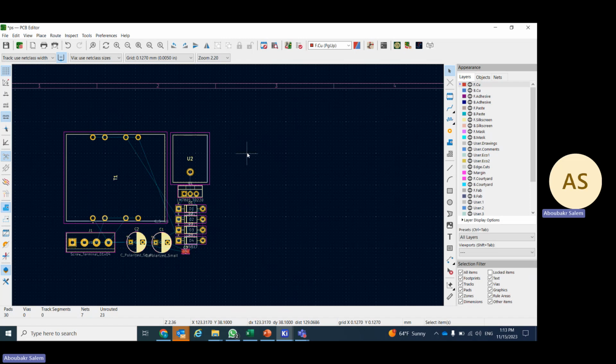Okay, so if I'm satisfied with the orientation like that, guys, let's make the border edge now. For the border edge, we should first select the edge layer. If you go to the right-hand side, you will find, where is edge here? Yeah, this is Edge Cuts. So I selected the layer of Edge Cuts, and I'm going to draw the border of this board.